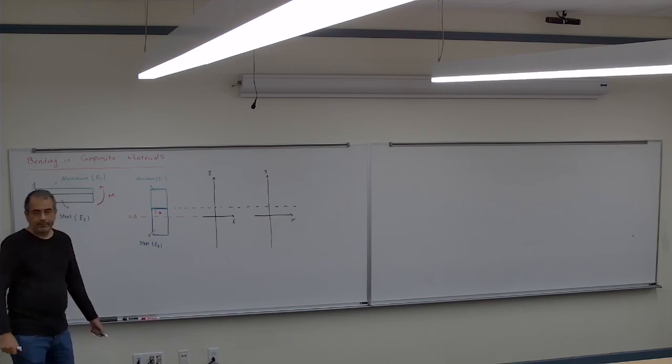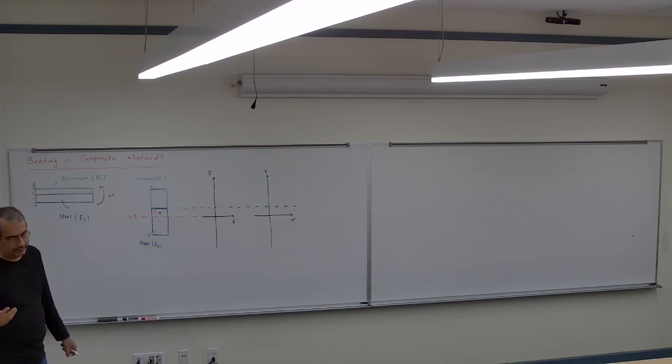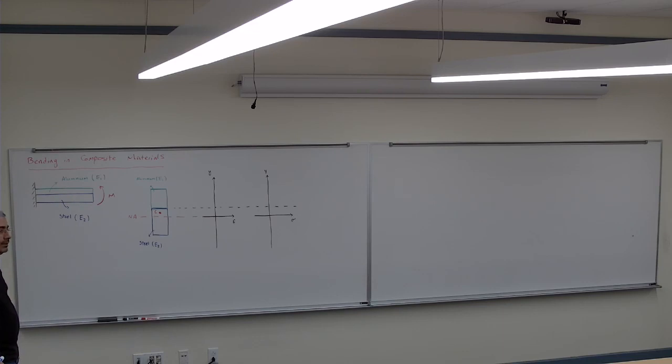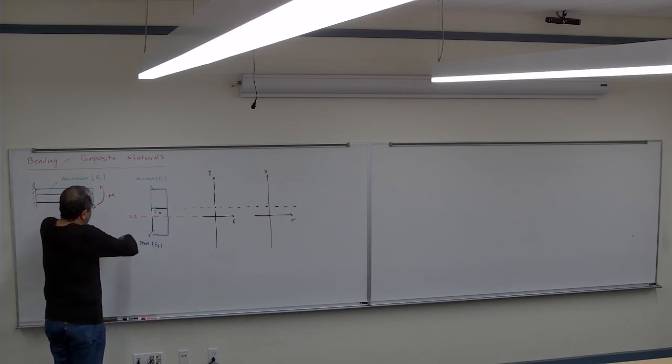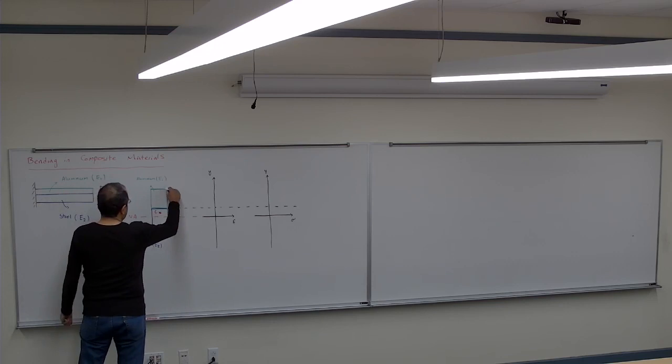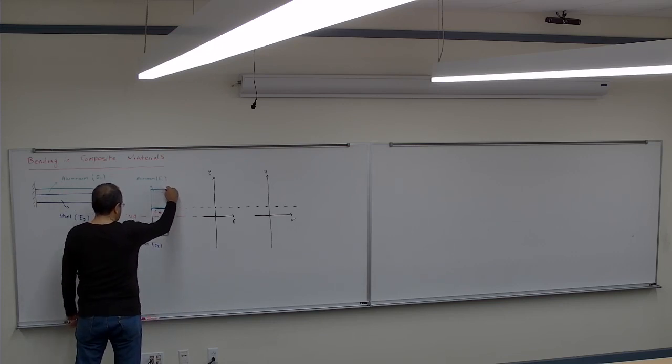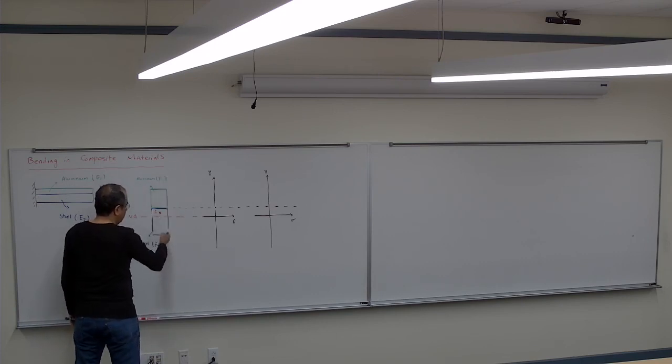So for the strain, steel is going to change linearly from the top to bottom. It doesn't matter, when I bend it, steel is going to be linearly compressed here and stretched here, and it changes linearly from compressed to tension.